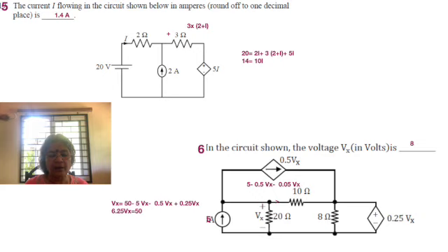Okay, anyway, let's see the different sources first. We have 2 dependent sources and both of them are dependent on Vx. Vx is the voltage across the 20 ohm resistor that we were talking about. There is a current source 0.5 Vx, horizontally displayed on the slide, and there's also a voltage source 0.25 Vx, which is again dependent on the same Vx. We also notice the 8 ohm resistor across it, which is of no consequence, as was mentioned earlier. So these things I'm pointing out again and again such that you remember.